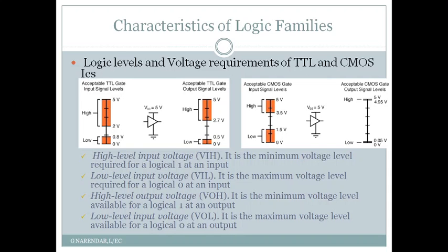So instead of choosing the exact voltages to represent the logic 0 and logic 1 levels, we'll use voltage ranges instead. We will choose a particular voltage range that represents logic 1, and a certain voltage range which represents logic 0.